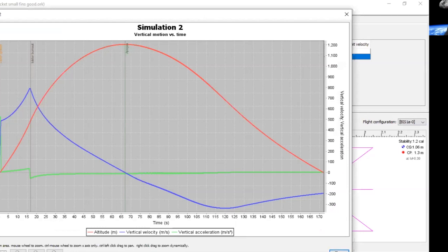So we've got a high acceleration when the motor was at high thrust, drops down after a second, and then carries on at low thrust, acceleration gradually increasing. Motor burns out, acceleration drops, and then continues. And acceleration gradually increases as we pass the apogee, because now we're coming back down again under gravity.